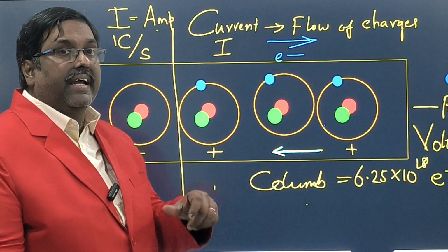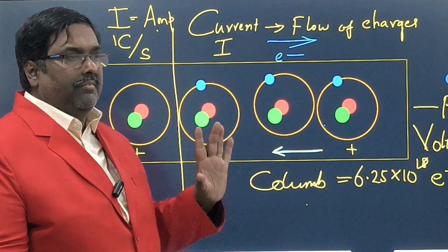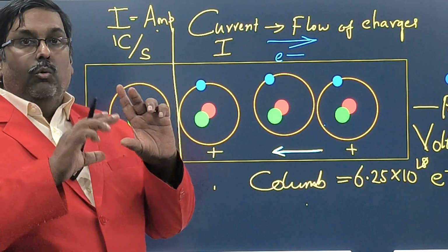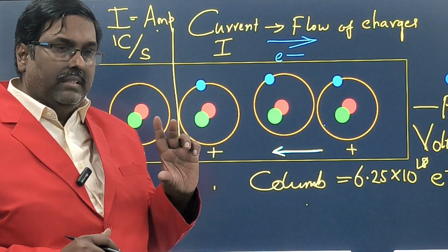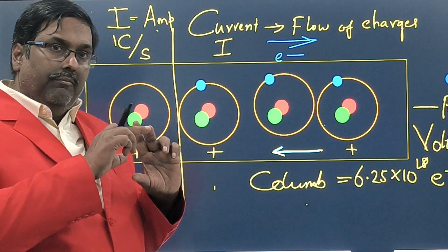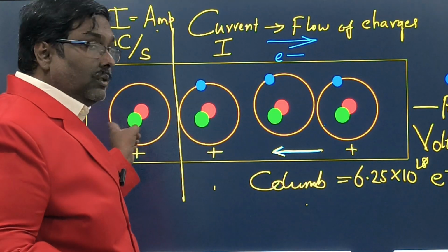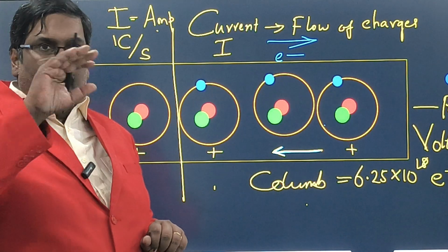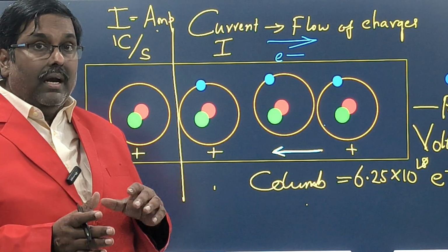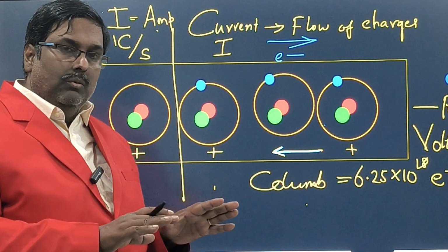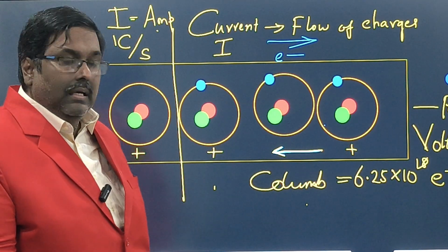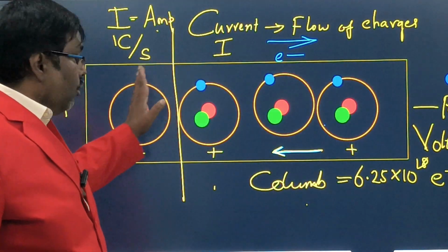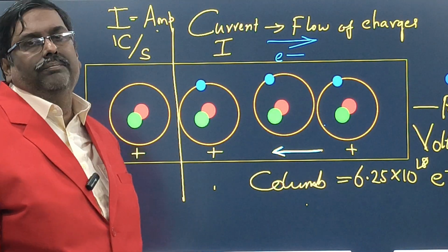Voltage is the force. It can be present without current also. If you take a battery, the positive side is high potential and the negative side is low potential. Voltage is present; if you measure it, 1.5 volt is there, but no current. For current, you have to make a conductor from positive to negative, and then the current will start passing. So without current, voltage can be present, but without voltage, current cannot be there. For increasing the current, we need more voltage. Less voltage will not move more current. So you have to understand this relation.